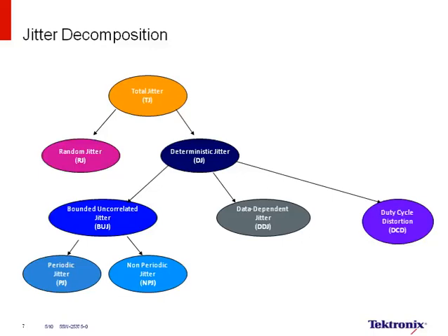The first level of looking at root cause of jitter is to look at the separation between RJ and DJ. So let's look at one leg of this slide here, which is the RJ or random jitter piece. This usually comes in general from silicon effects. So this is things like white noise, flicker noise, shot noise from the RJ. And so really what you're asking for is, well, how do I fix this?